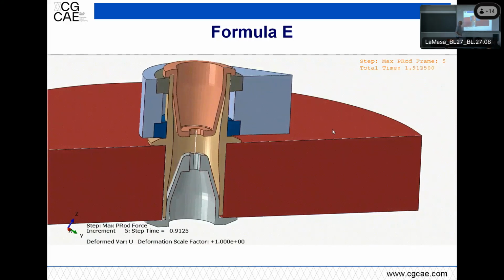And this, again, is not good for different reasons. For compliance, but also having a hit there would have worn out the insert, and this is a problem because the insert is inside the casing and you cannot replace it. What you could do would be to maybe weld something on, and welding aluminum is not the nicest thing.